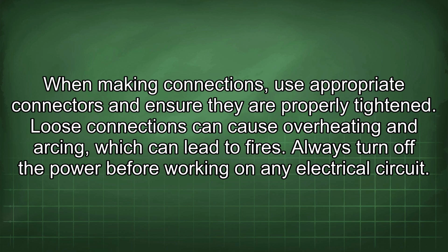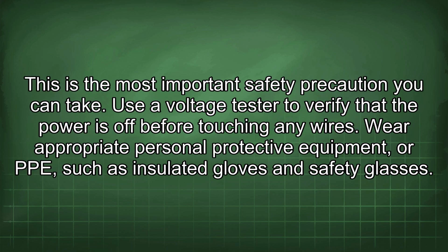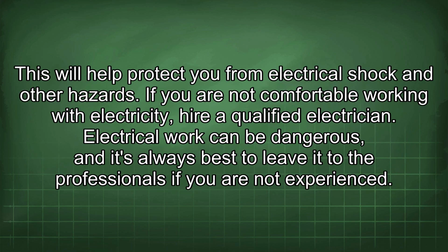Always turn off the power before working on any electrical circuit. This is the most important safety precaution you can take. Use a voltage tester to verify that the power is off before touching any wires. Wear appropriate personal protective equipment, or PPE, such as insulated gloves and safety glasses. This will help protect you from electrical shock and other hazards.